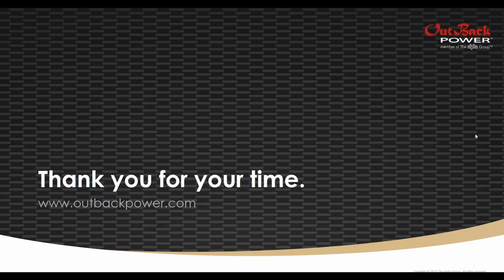Rob asked for a clarification on rapid shutdown. So with a traditional DC string inverter using an OutBack Power ICS Plus system and RSI, SkyBox is directly compatible and NEC compliant to this solution. Yes, absolutely, Rob. That being said, you wouldn't use the OutBack Power ICS Plus for your traditional NEC 2014 rapid shutdown solution.